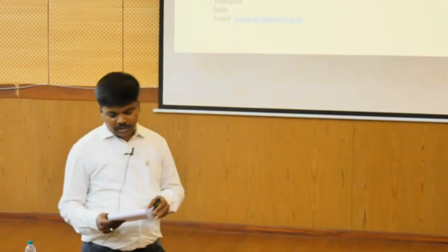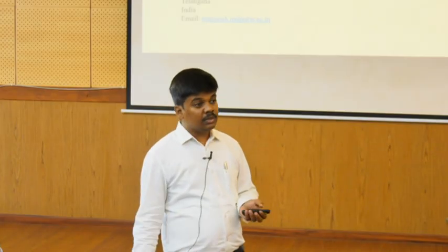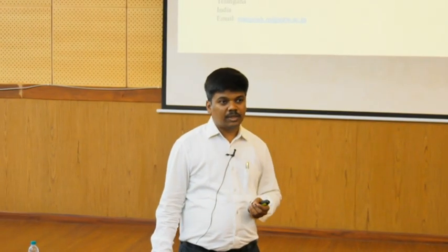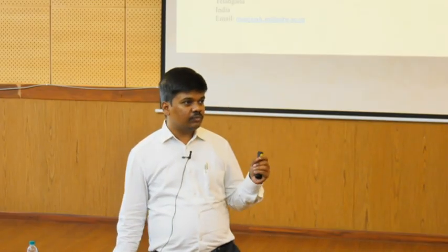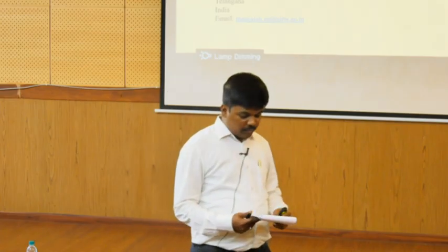That is what we need to think of. Even for the gas production, people say the global average cumulative energy demand for nitrogen is almost 6 megajoules per kg. If you want to generate 1 kg of nitrogen gas, almost 6 megajoules are required. That much energy is required. Then for argon, they have reported almost 38.6 megajoules per kg. It means if you want to generate that much argon gas, we need to spend 38.6 megajoules of energy.